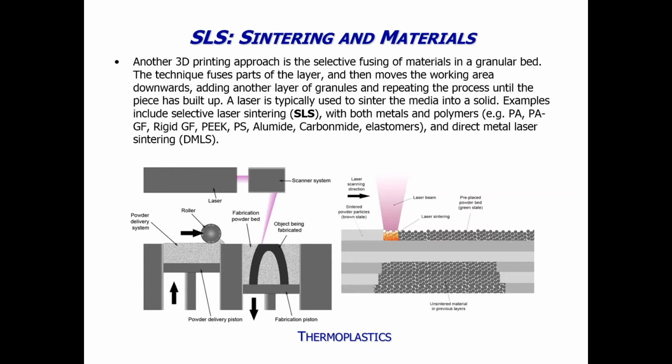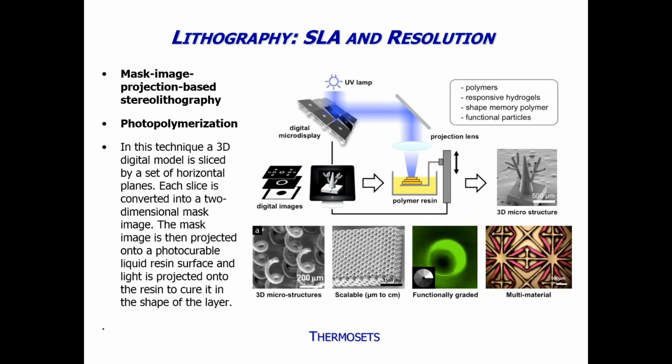So this example, which I showed earlier, is based on photolithography. So photolithography means that you use light to enable polymerization or photopolymerization of a resin composition that contains a monomer, a dimer, or a cross-linker, and diluent monomer, or additional additives that enable nanocomposites or better 3D printing properties.